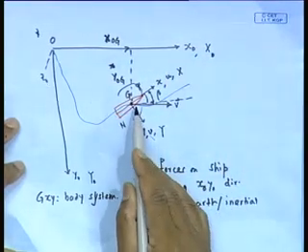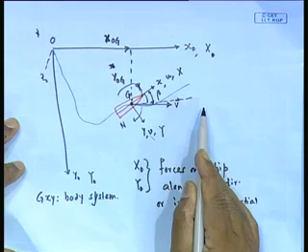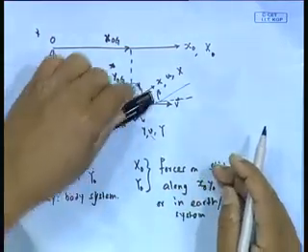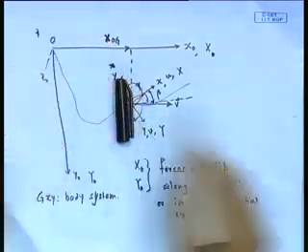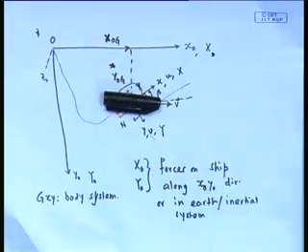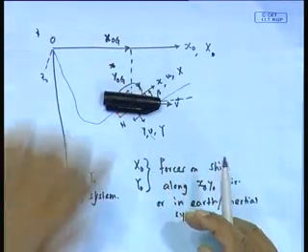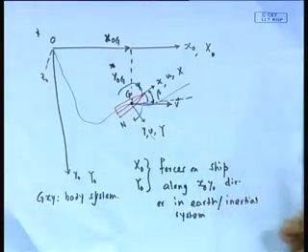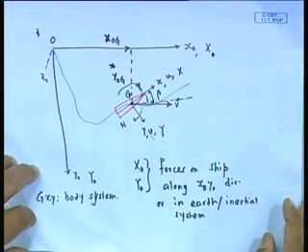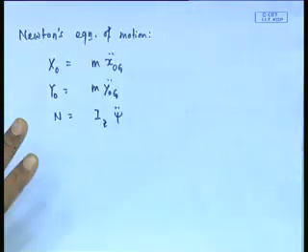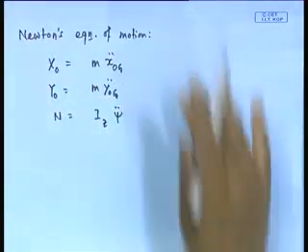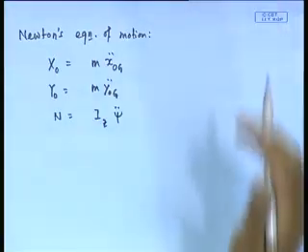So, if I were to do along this x0 axis, it can be arbitrary depending on the orientation. Tomorrow the ship might be oriented this way, then my x0 force becomes actually sway force, then next instant it is this way, my x0 force becomes my surge force. So it becomes difficult to define, that is why I need to transform them to this x and y axis. That is the thing that we will be doing now slowly, transforming this to that axis. How do I do that? It goes actually using this transformation matrix.